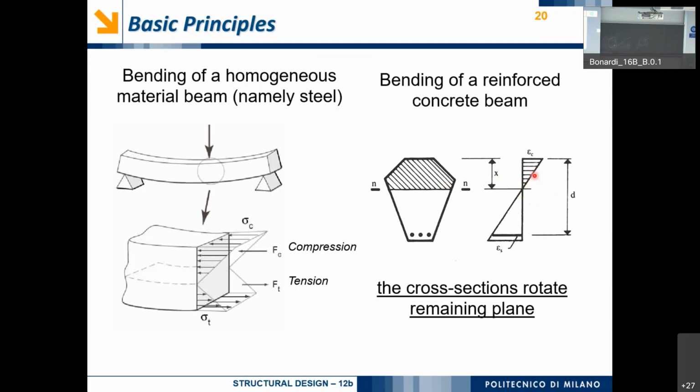the deformed cross-section. In fact, we have seen here that under bending we will have some deformation of the area, and we can imagine that of the cross-section, and we can imagine that the upper part tends to exert compression, and the bottom part is showing elongation.